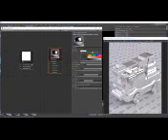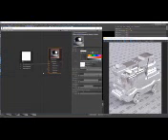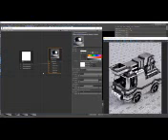And now connect the ambient occlusion map to the reflection color input. And as expected, the ambient occlusion map controls the reflection, and where the map is black in the corners we get 0 reflections, and obviously where it's white, we get a fully reflective surface.